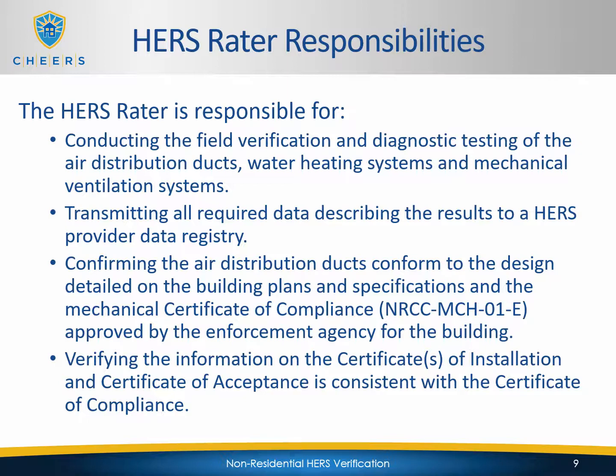So those forms, the NRCC, NRCI, and NRCA, do not exist in the registry. So unlike residential, where all the forms are located in the registry, for non-residential, at this point, only the certificates of verification are going to be in the registry itself. So you have to do all of this review of the documents outside of the registry. They'll be all part of the plan set for the building, and so you'll need to get the certificate of compliance from that, and then the other ones from the installing contractors.